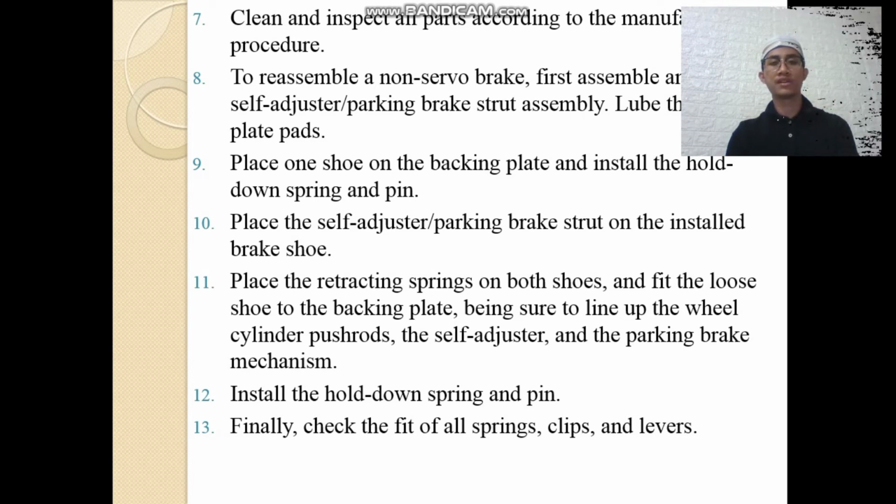The eighth step is to reassemble a non-servo brake. First, assemble and self-adjust the parking brake strut assembly. Lube the backing plate pads. The ninth step is to place one shoe on the backing plate and install the hold-down